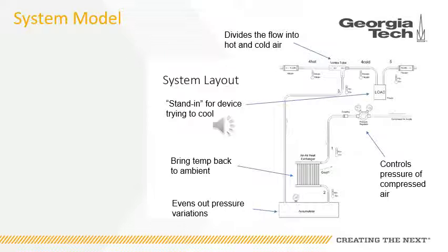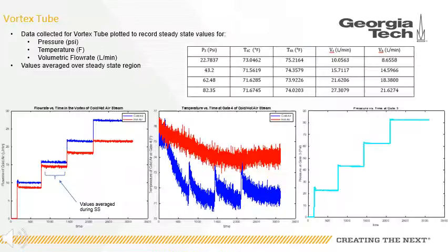Flow rate sensors are present at the outlet of each exit point of the system to measure the rate at which hot air and cold air exit the cooling system. For this first week of testing, we focus exclusively on the cooling system, using a stable, building compressed air source. As the air is pumped through the system, data on the temperature, pressure, and flow rate are captured.